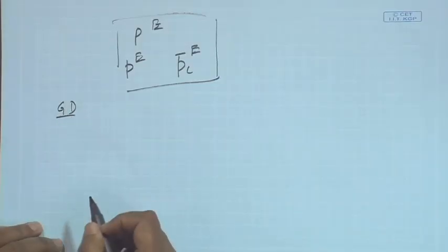So, since finding out gamma is so very important as far as vapor liquid equilibrium for non-ideal solutions is concerned, and we come across non-ideal solutions very frequently, it is important to express the Gibbs-Duhem equation in terms of gamma, so that for a binary solution, which we usually come across, if we know gamma 1, we will be in a position to find out gamma 2. Let us start from the beginning and see how we can derive the Gibbs-Duhem equation in terms of gamma.